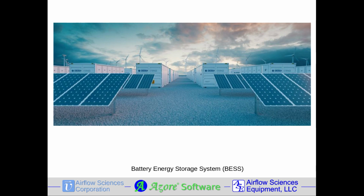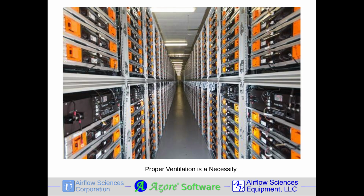to optimize their generation output. One solution is load leveling, in which generation units run at a more consistent output, and surplus energy is stored when demand is low. When demand increases to peak levels, the stored energy can be discharged. A battery energy storage system, or BESS, is one method to store surplus energy and respond to variable demand.